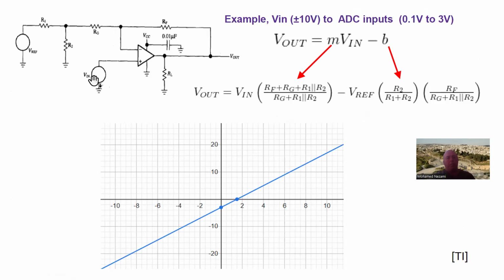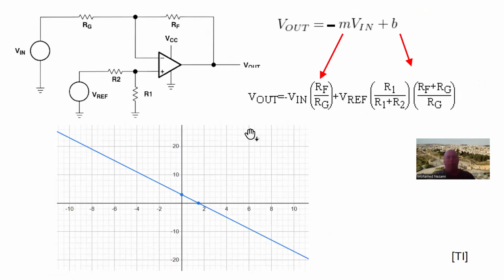Now, as far as the reference voltage, oh, I'm sorry, that's this one here we're talking about. This is negative. The input is the same way, except it's positive. And we can do the same thing for the other two, one where it's negative gain but positive reference. So the reference is on the positive port, and the input is on the negative one. This one is much simpler because Vn goes in here. So this is just an inverting op amp, which is just this resistor over this resistor. Now this voltage gets divided between these two resistors, so the first thing is we have to multiply by this to get the actual voltage at this point here.